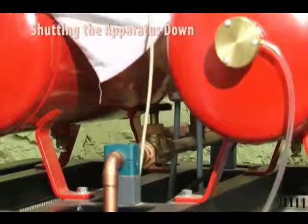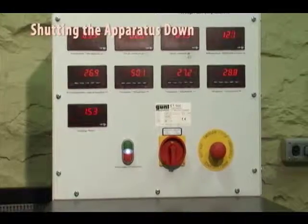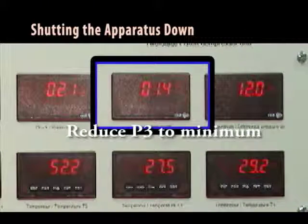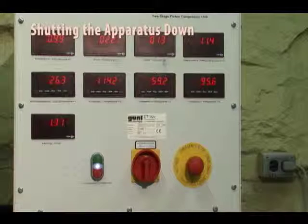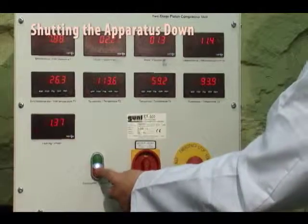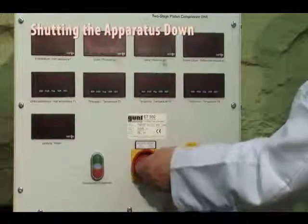Shutting the apparatus down. Using the throttle valve, reduce the pressure P3 to the minimum. Always press button 0 on the compressor switch first to activate the ventilating valve. The ventilation valve ventilates the line to the compressor, making it easier for the motor to start up.